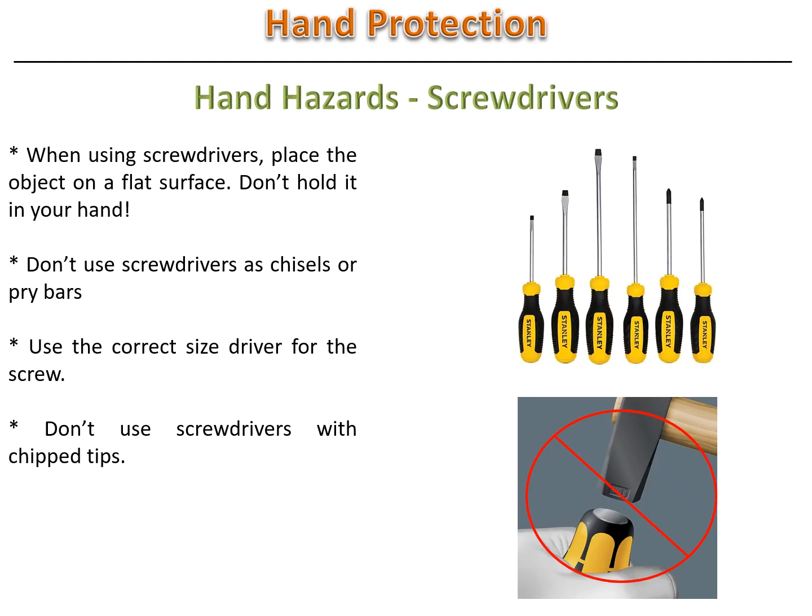Hand hazards: screwdrivers. When using screwdrivers, place the object on a flat surface. Don't hold it in your hand. Don't use screwdrivers as chisels or pry bars. Use the correct size driver for the screw. Don't use screwdrivers with chipped tips.